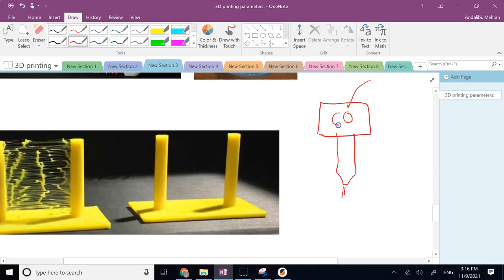And then using two gears, the idler mechanism and the gear that is attached to the motor, it brings it to the heat sink and heat block here, right? And then it puts down the molten plastic on your object, on your print bed.